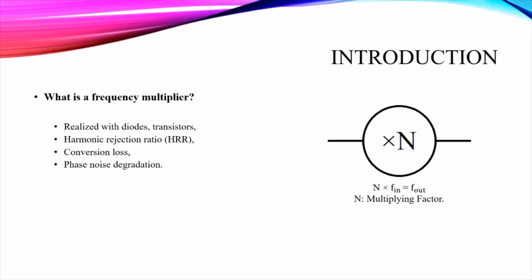Frequency generation is an important part of millimeter wave and microwave wireless communication systems. Voltage-controlled oscillators generate high-frequency signals directly by employing an oscillator tuned at the fundamental frequency. However, VCOs need high-quality varactors for their performance. Moreover, they are governed by constraints including low output power, phase noise, jitter, stability, and high cost.